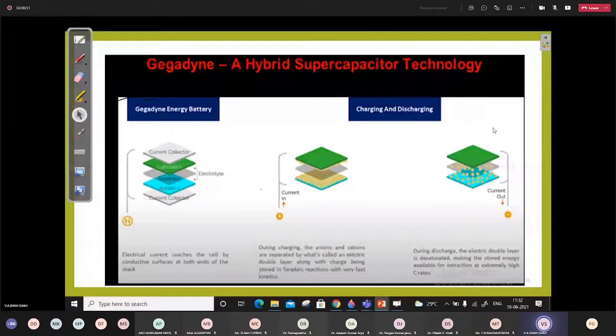The disadvantage is that two full size converters are used. Converters add weight, cost, size and complex control. And this is a multiple converter configuration within one single unit, and battery and supercapacitor can be connected like this. This will overall reduce the cost of the two full size bidirectional converters that are used.